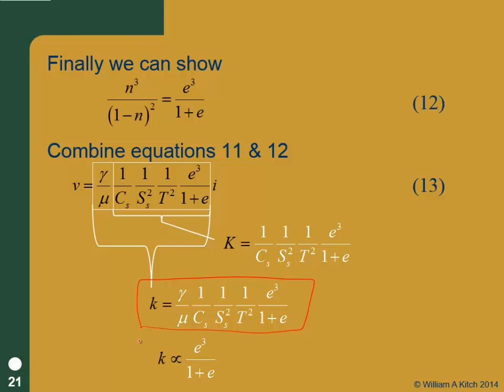It's a really easy paper to read, and it shows you how you can actually calculate the hydraulic conductivity for a soil. You can estimate these parameters through grain size distribution, and you can estimate hydraulic conductivity for coarse-grained soils if you know the grain size distribution, and all you need to figure out is how you get a compaction and a void ratio. And it works as well as anything that we've got to estimate hydraulic conductivity. Now we're not doing just a correlation with something. We're actually measuring real properties.